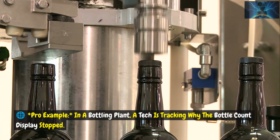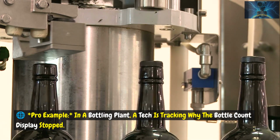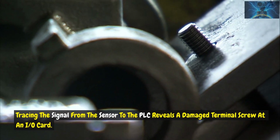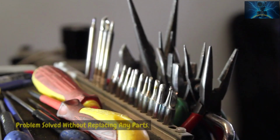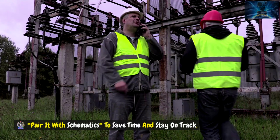Pro example: in a bottling plant, a tech is tracking why the bottle count display stopped. Tracing the signal from the sensor to the PLC reveals a damaged terminal screw at an I/O card. Problem solved without replacing any parts. Pair it with schematics to save time and stay on track.